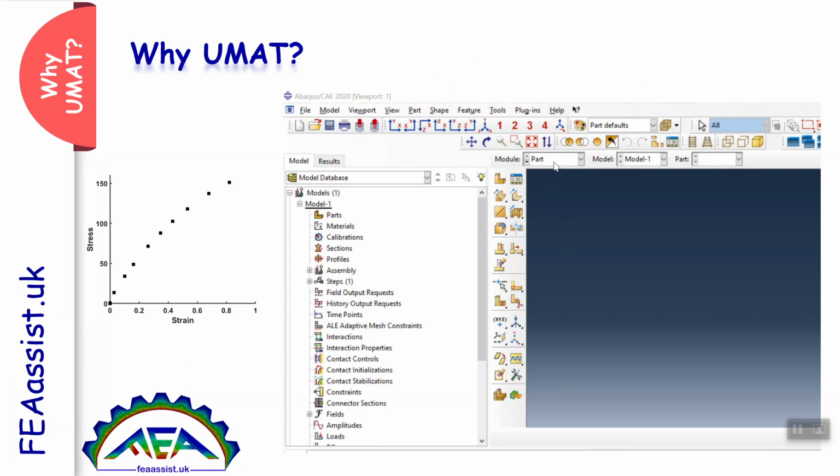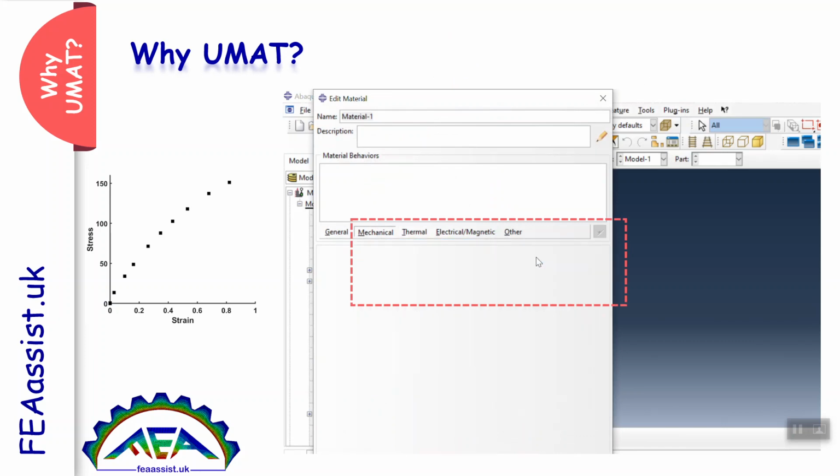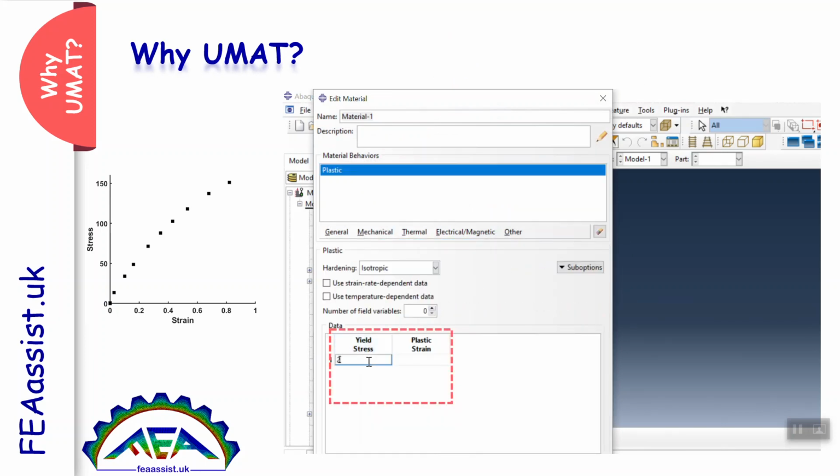You can easily go to Abaqus, to the property, define a new mechanical behavior, plastic behavior, and enter those points like this. This is the simplest way of solving the problem, but it is not precise because Abaqus interpolates between these points and solves the problem in all points.